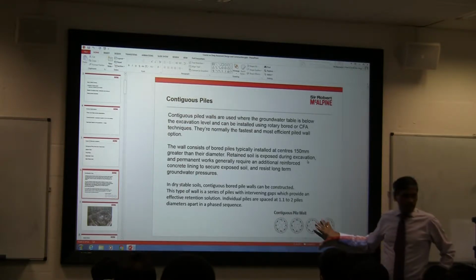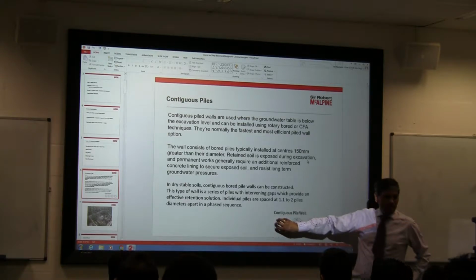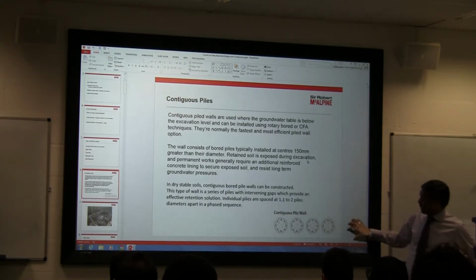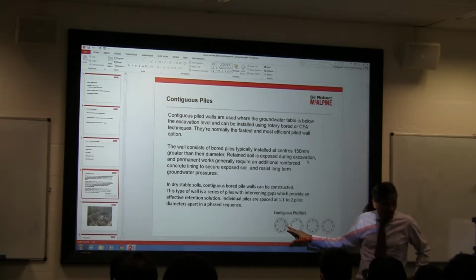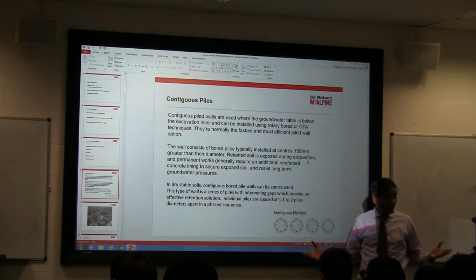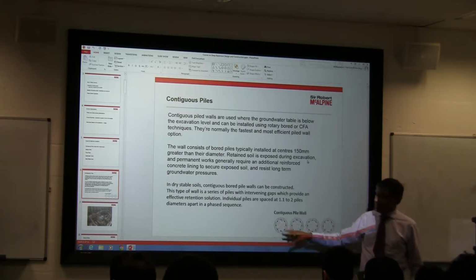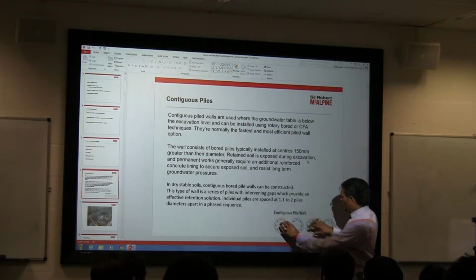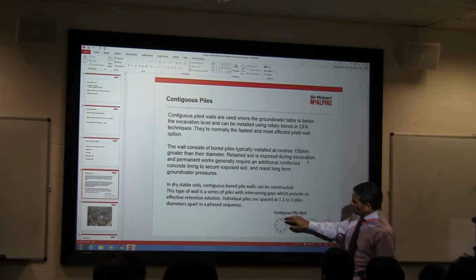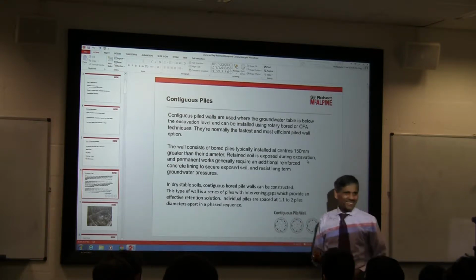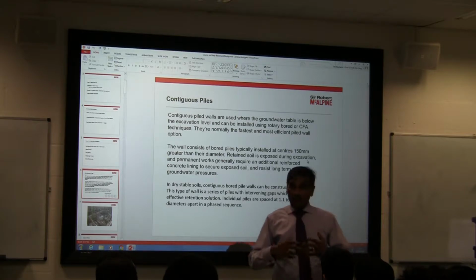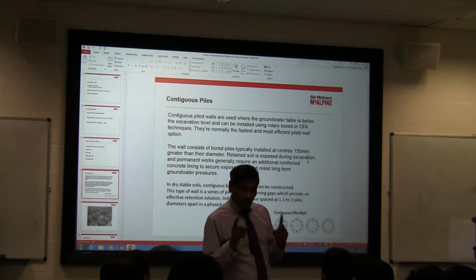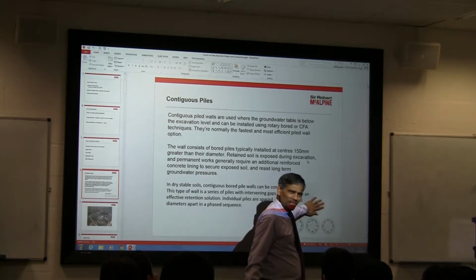This is all ground, yeah? So we're going to drill this pile, come back and drill that pile, come back and drill that pile, hit and miss. In between these two, the soil will hold. The soil is still here. So when I drill this pile, then that pile, and come back and do this pile, between those two the soil will arch. So I'm making use of the ground being good, so that it can arch, assuming there is no water on this side.